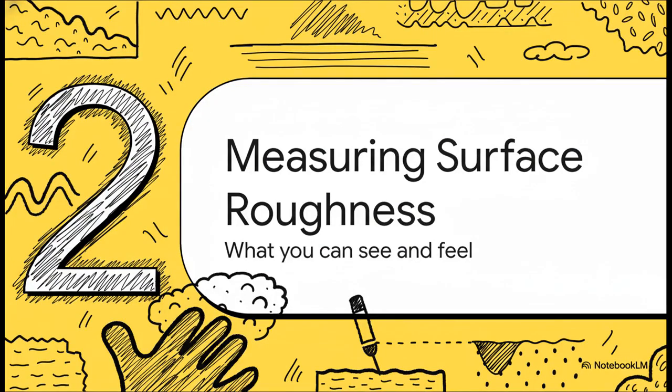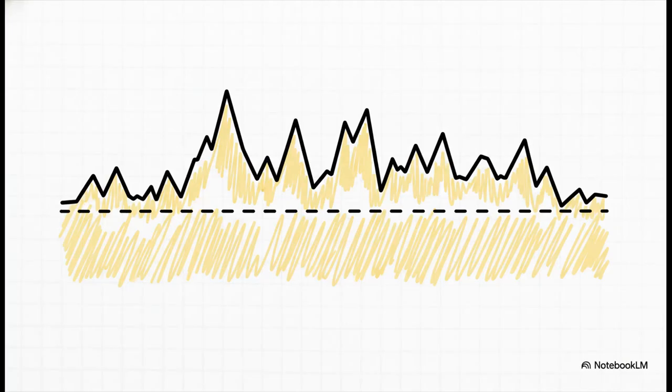So our investigation kicks off at the most obvious layer, the surface texture. This is the part we can actually see and feel. But to really get what's going on, we need to measure it with some serious scientific precision. And the key metric here is something called Ra, which stands for arithmetic average roughness. The idea is actually pretty simple. If you imagine the surface as a microscopic mountain range, Ra is just the average height of all those little peaks and valleys. It boils all that complexity down to one powerful number that describes its texture.